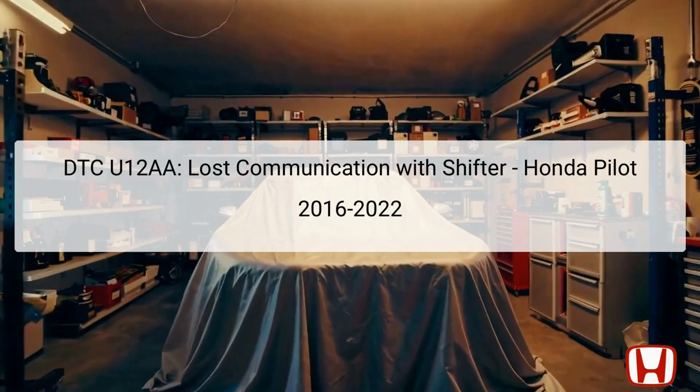The Diagnostic Trouble Code, DTC U12AA, indicates a communication loss with the shifter in Honda Pilot models from 2016 to 2022. This error signifies that the vehicle's transmission control module, TCM, is unable to receive or send signals to the shift-by-wire (SBW) shifter control module, which manages the transmission's operation. Effective communication between these modules is crucial for proper gear shifting and overall vehicle performance.